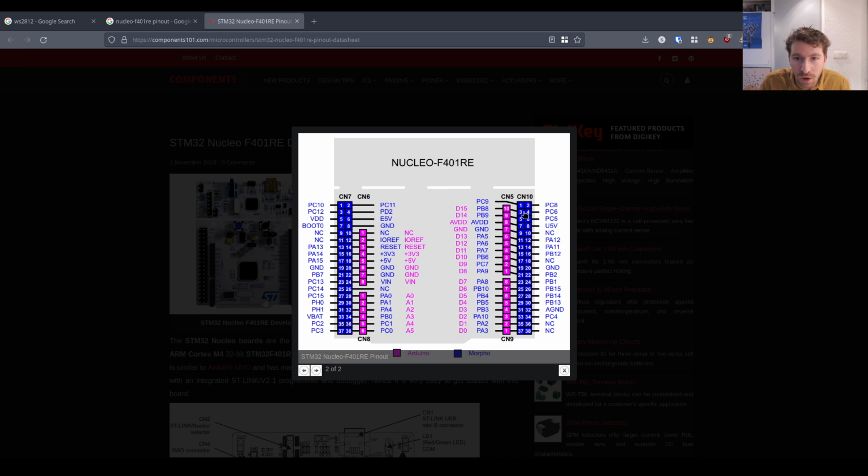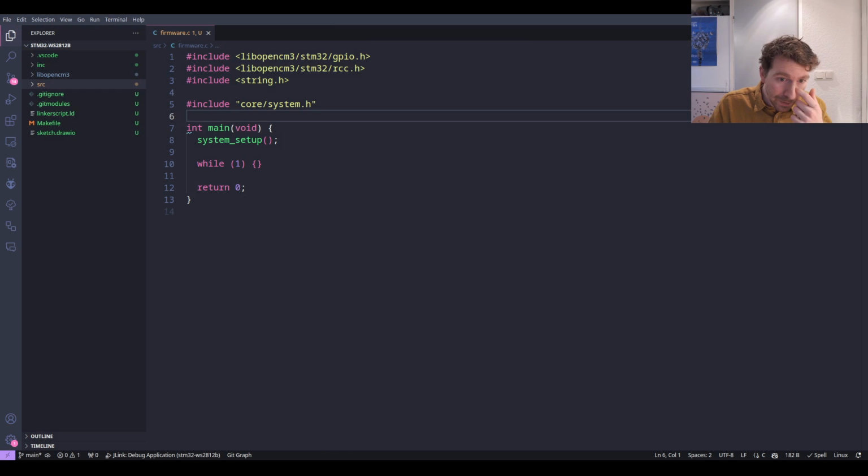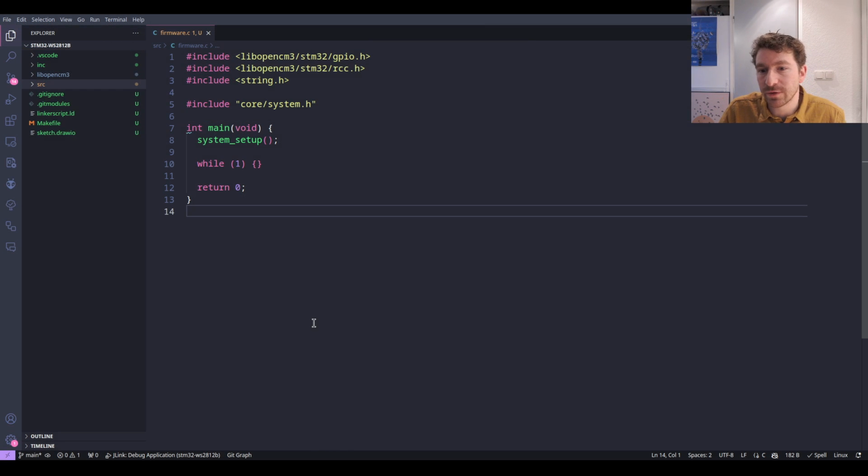I'm just going to arbitrarily choose it now. And now is a good time to mention that the way in which we're going to generate this signal is through a technique called bit banging. If you've never heard of it before, all it means is that we're going to generate the signal by writing code using the CPU, basically. We're going to use the CPU to generate the signal.